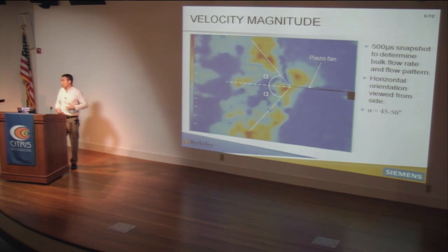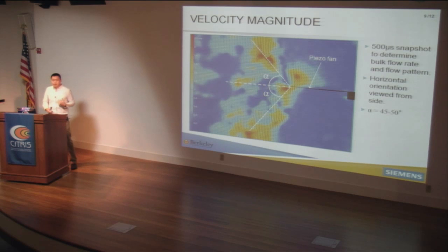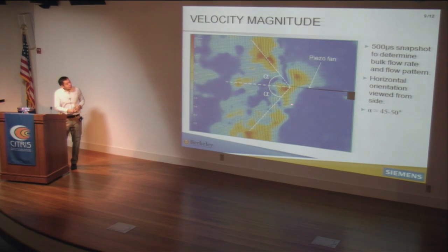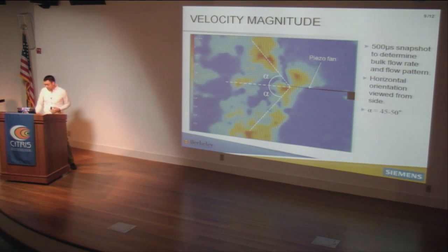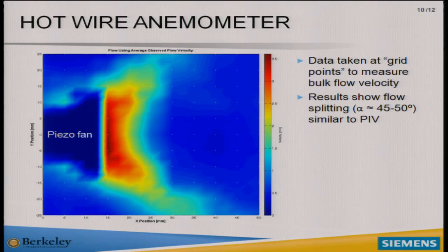If we go back to earlier, where we were talking about coverage at 25% or 12.5% in a vertical orientation, you can imagine this block around here. When the air spits off at this angle, at 25%, most of the air actually hits the heated surface. When you're too far down here, you don't get enough cooling. When you're too far back here at full coverage, a lot of the cooling, the high velocity, isn't touching the surface. We were able to confirm this again using a hot wire anemometer, where we had this fan.